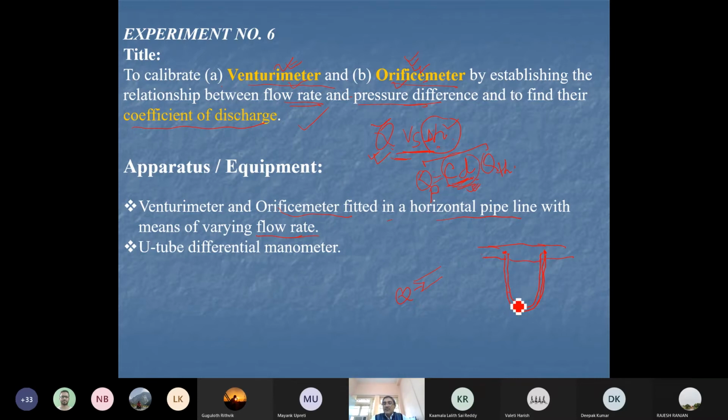So here we are usually using a heavier fluid, or any fluid we can have of different characteristic than the flowing fluid. Here mostly mercury is used. Suppose the pipe is flowing in this direction, this is the discharge side, and you are measuring the pressure head at these 2 points, neglecting the head loss due to friction, because these are 2 points very near to each other. We simply find this is P1, pressure 1, and P2. So P1 is always higher and P2 is lower in a simple pipeline.